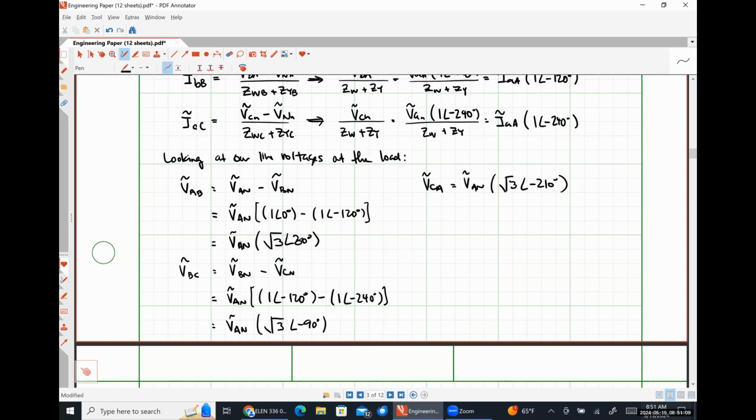What about the line voltages at our source? Well, lowercase van, vbn, and vcn all represent balanced voltages as well. So those line voltages will also be a balanced set of voltages having the same magnitude and 120 degrees of phase separation.